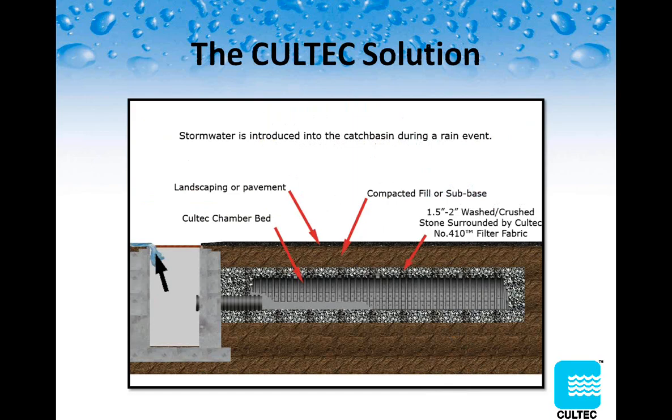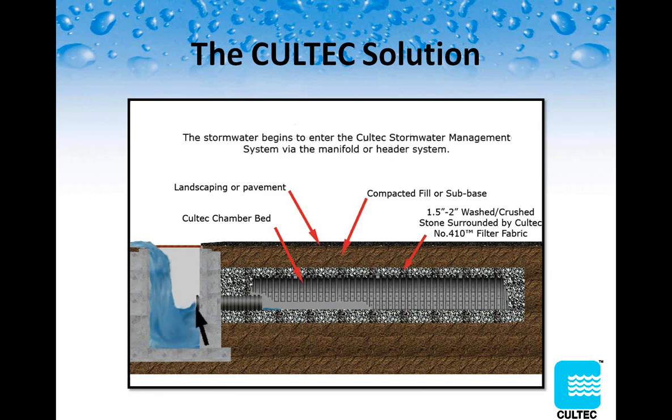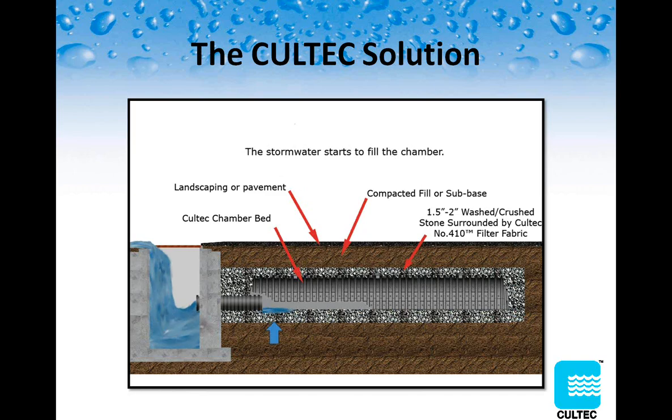Basically, the simple operation of how our system works: water would enter in from a collection source such as a catch basin, and it would exit out into our manifold system, which would bring the water into our storage chambers.